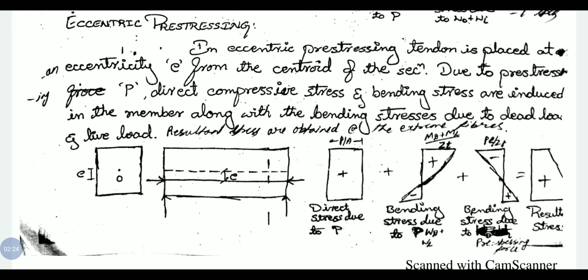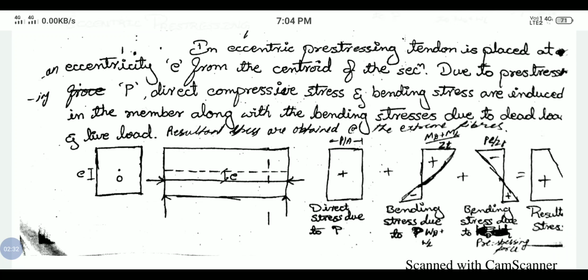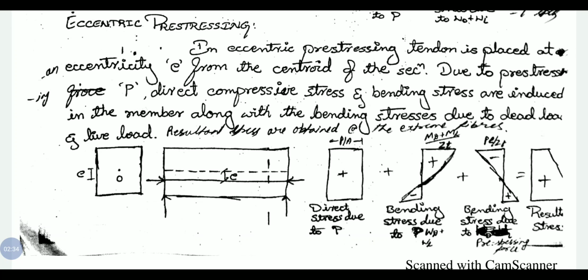So, in addition to direct stress due to pre-stressing force and bending stress due to dead load and live load, we also consider bending stress due to pre-stressing force.